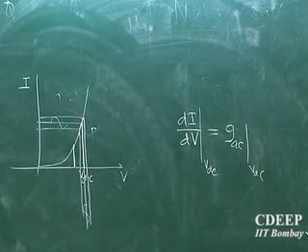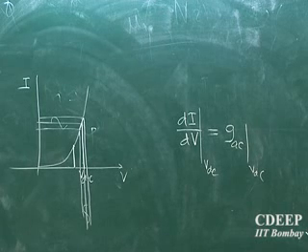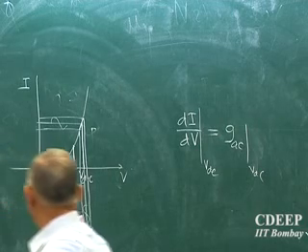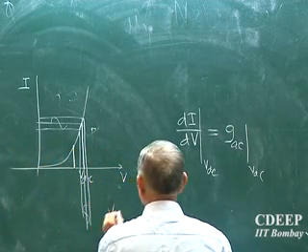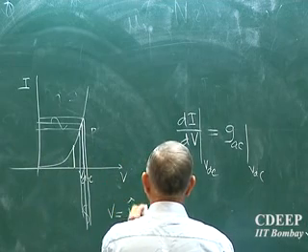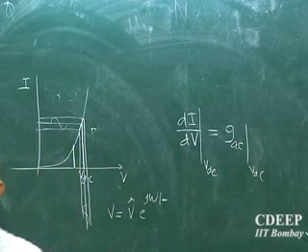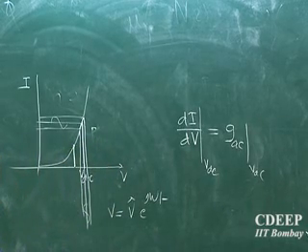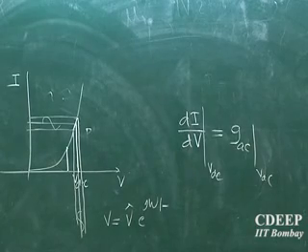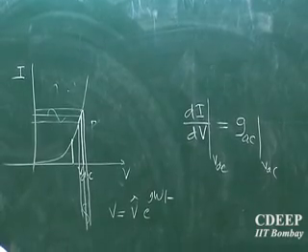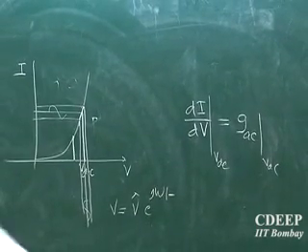But for the same DC V, R is known. That can be the AC resistance or the AC conductance. Is it clear where the AC is coming from? Because I apply a small signal, which we can say is a phasor e to the power j omega t, then I figure out that a small change will result in the equivalent of a slope there, which means AC resistance. So a diode has an equivalent AC resistance.